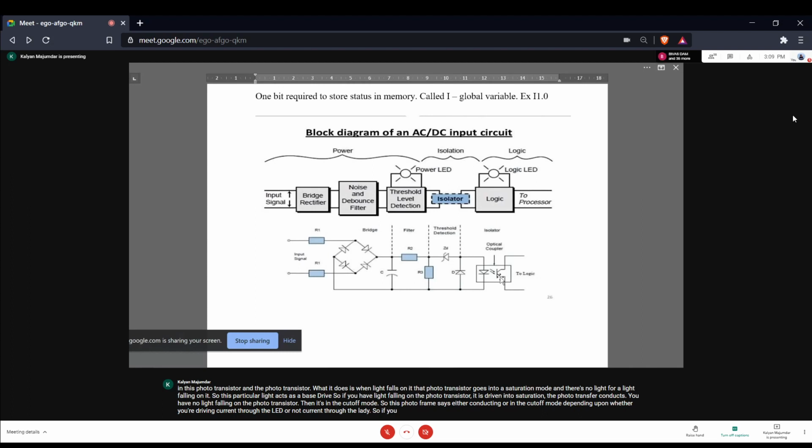Look, there's absolutely no electrical connection between the LED and phototransistor. They are two completely independent devices within a housing with a common casing. If you measure continuity, there is none. The information here is optically coupled between the input and the output. In a transformer, it's magnetically coupled. So this is galvanic isolation, that is, you convey information from the input to the output, and the output in turn connects to the processor.